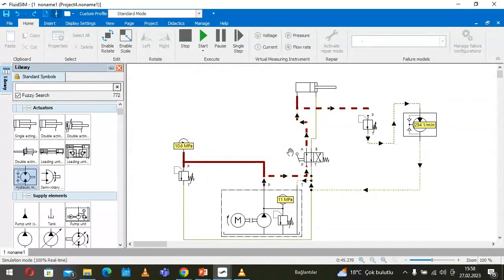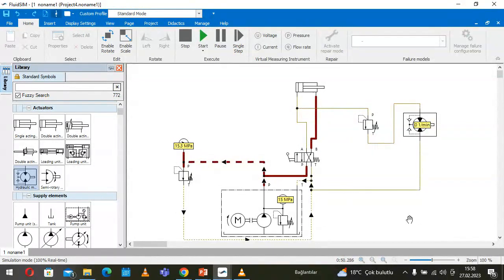Okay. We use in the same circuit a linear actuator and a rotary actuator, in connection. That means, let's say we have a workpiece here, and the workpiece has to be clamped by this linear actuator, and then the motor has to start after clamping is finished, to cut a screw or to cut something, or to do any initial work based on the rotary motion.